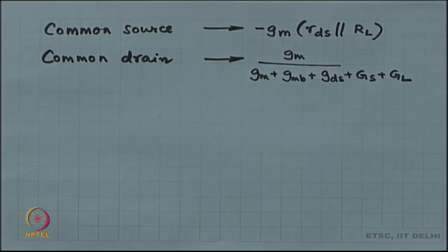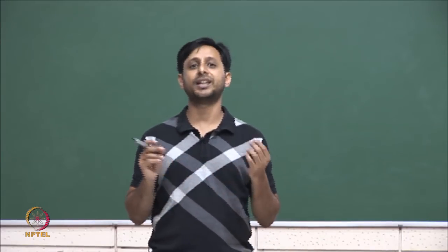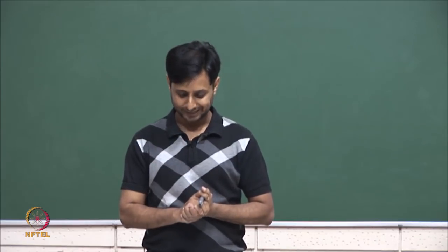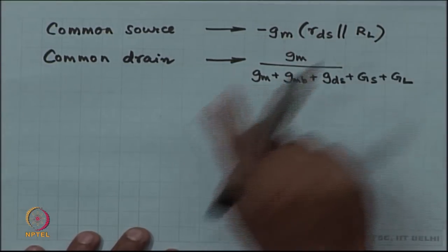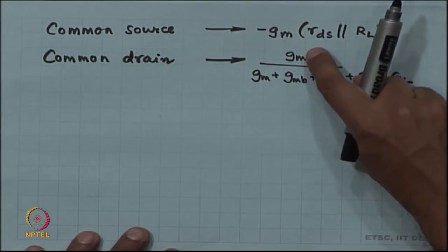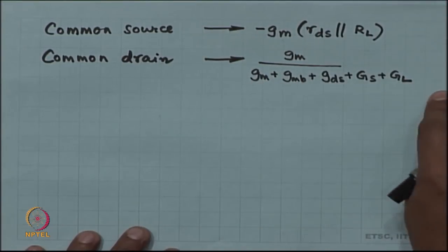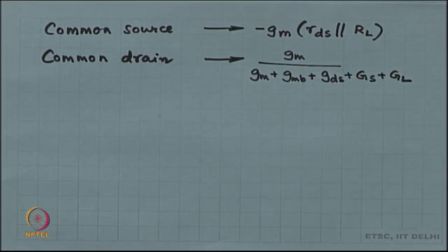Notice in analog circuits you try to keep the dimensions, not just in analog circuits. Dimension analysis is a very straightforward way of checking the authenticity of the answer. So, look at the dimensions, right. First of all, you are talking about a voltage gain. If you talk about a voltage gain, then the overall dimensions will be dimensionless. So, I have got GM multiplied by some resistance, no dimensions. Here voltage gain, it is a conductance divided by conductance. Okay. So, keep track of the dimensions, it always helps.